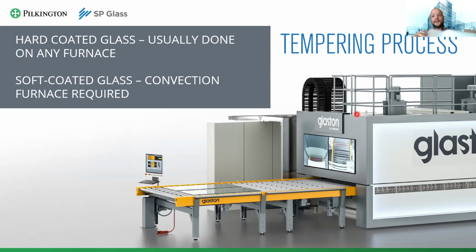But when the facade is bent inwards, it's time for the hard coating, because that means the coating has to be positioned on the bottom of the glass, and soft coating does not survive the tempering process and bending in this regard. The same applies if you have a double bent facade, so some parts of it are bending outwards, while the others are bending inwards. I am afraid in this case, you have to use hard coated glass, which, mind you, Pilkington has plenty of. Just not produced in our factory.